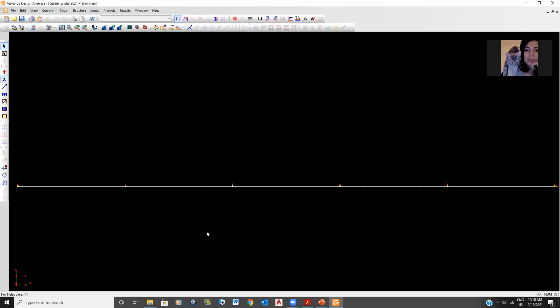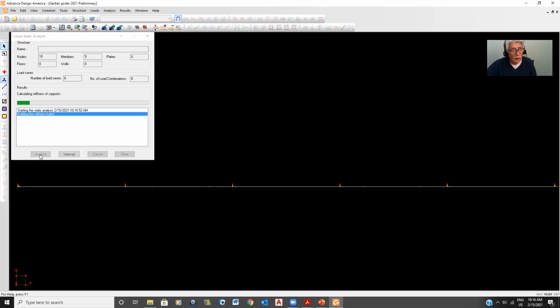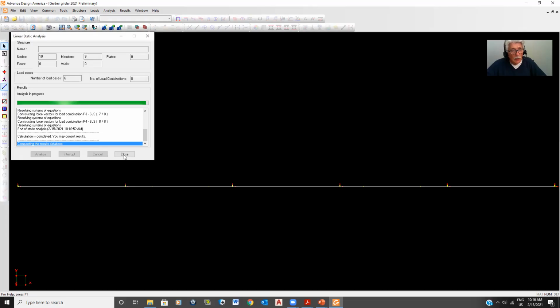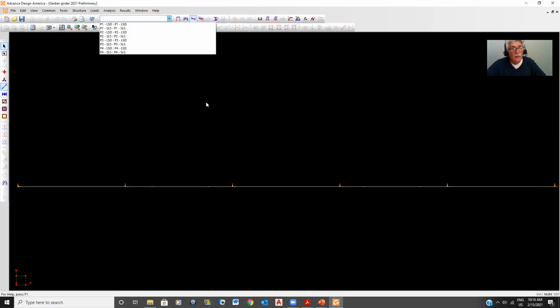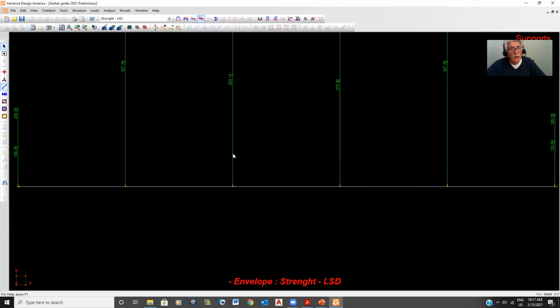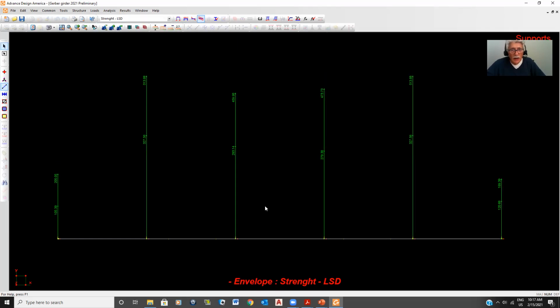Okay, so now everything is good. I got my load combination. I got my envelopes. I got my load case. And of course, I want to run some analysis. Okay. And I close this. And of course, since I've got an envelope, I'm going to go to envelopes. I'm going to go to strength. Now, guys, the first thing I like to look at is always my reactions.